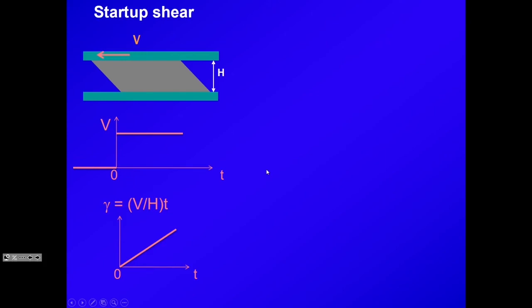In the sense that it's hard for me to demonstrate with this PDMS the recoverable part of deformation. In other words, when I stretch, well, you can see it recovered a little, but hardly any. Yeah? I mean, I do the best I can, a little bit. Which means, yes, for this polymer, because it's so fast, and I was doing 3 seconds, and this thing is relaxing in 1 second, so quickly I reached the irrecoverable deformation limit, or flow limit.